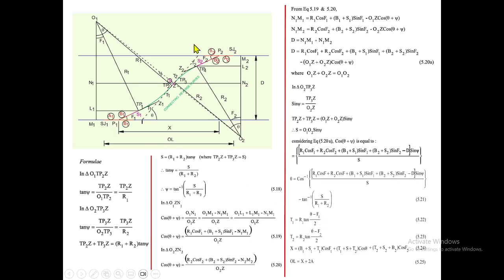Okay, like that. So T2 is equal to R2 tan of the deflection angle. Here already you know theta minus F2, that is the angle subtended at center, that will be your deflection angle here, theta minus F2. So T2 equal to R2 tan theta minus F2 divided by 2. Okay, got it. So once we know the tangent length, we can now make some triangles where we can find the horizontal distance from the point of intersection of this point to the point of intersection of the other points.